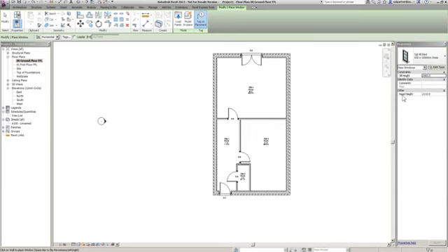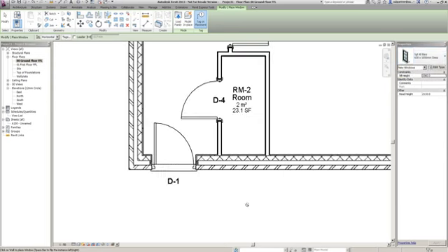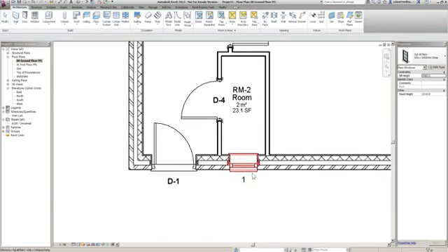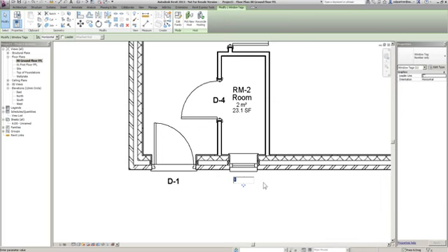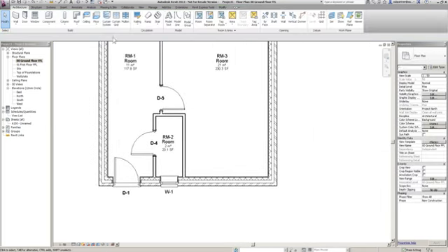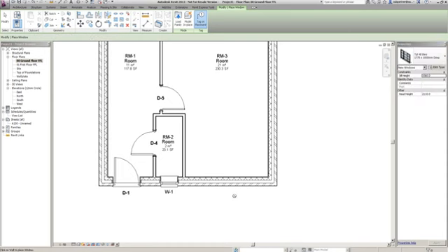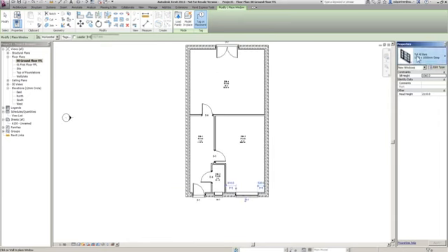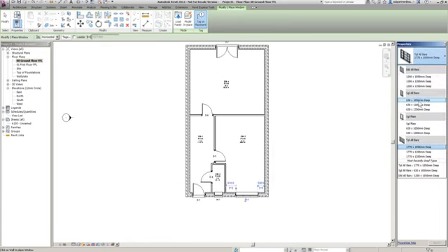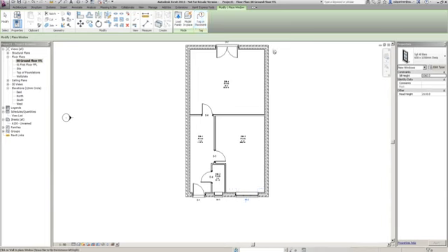I'm just going to throw in a small window just here of 1050 height, at a head height of 2110. I'm just going to place my first window just centrally within the room just there. And just like with my doors, I'm just going to call that one window 1. Fantastic. Okay. Again, I'm going to go window, and this time I'm going to pick a triple window to place in my kitchen down here. Fantastic. Window 2.